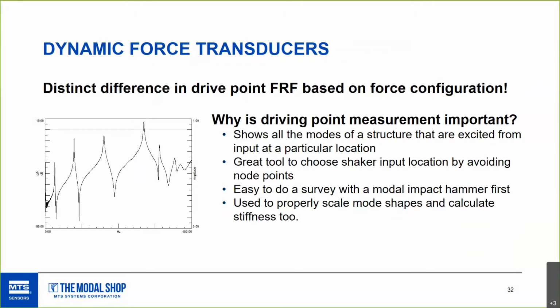So it's easy to use a modal hammer and co-locate an accelerometer close, or if you have a panel where you can impact with a hammer on the other side, make some quick driving point measurements. But also when you get more into the math side of it, this is used to properly scale your mode shapes and calculate stiffness. So that's another reason for paying attention to having good mounting of your force sensor and stinger combined.